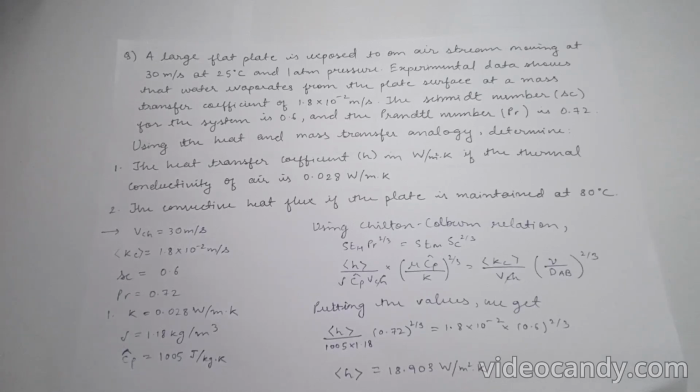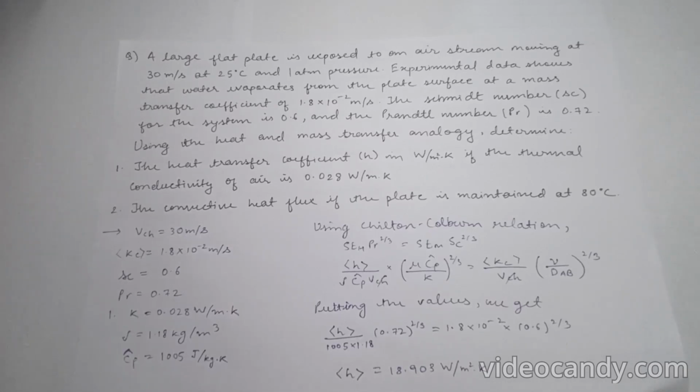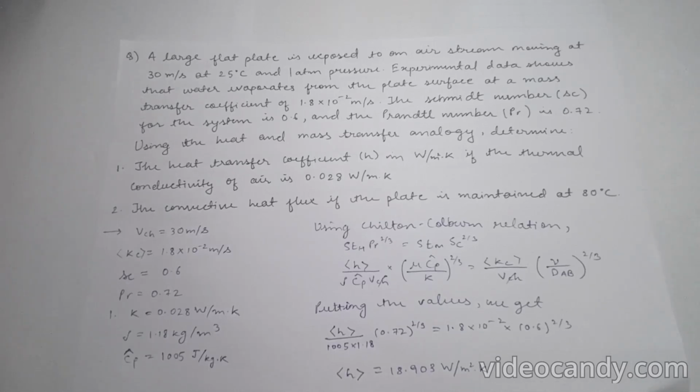The second condition is a wide range of flow conditions. Unlike the Reynolds analogy, which assumes a close relationship between heat and mass transfer, the Chilton-Colburn analogy can be applied to both laminar and turbulent flows with different fluid properties. The third condition can be non-ideal conditions.